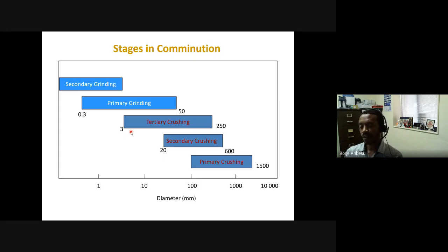And therefore, if I want it for road making, for example, I smash the rock, produce large pieces of rock, and then I have to do screening to work out the best range of particle size I want to use for road making. Usually they screen, and they use both the coarse and the fine. The fine is usually the one that can go for road making. The larger rocks can be used as building blocks, for making buildings and so on.